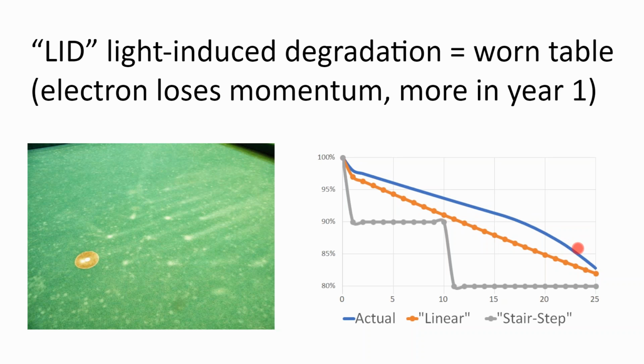That 0.5% degradation is just from weather, humidity, water getting into the seal of the solar panel and then being vaporized and leaving little blotches that make the electrons not flow as well. I'm going to talk about warranties in a little bit.